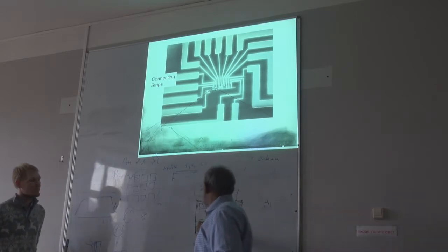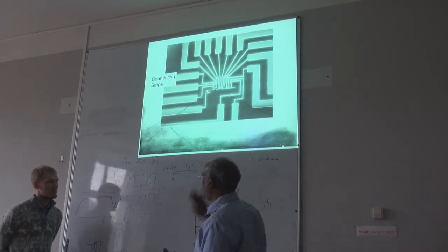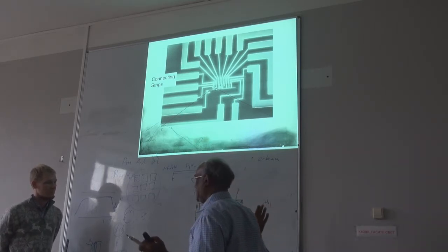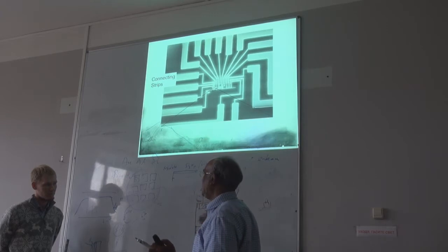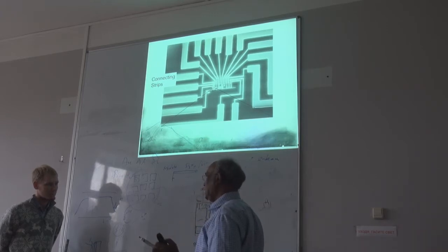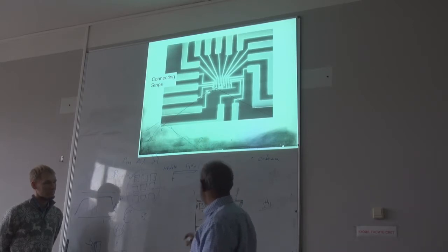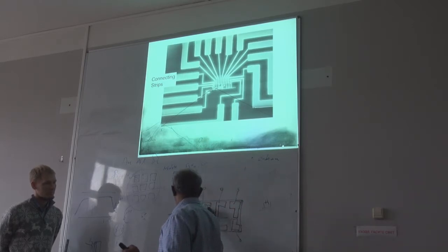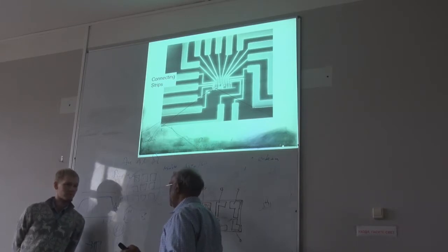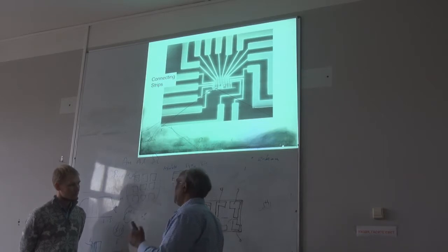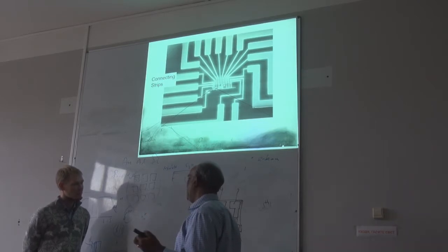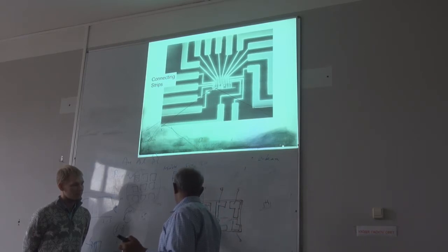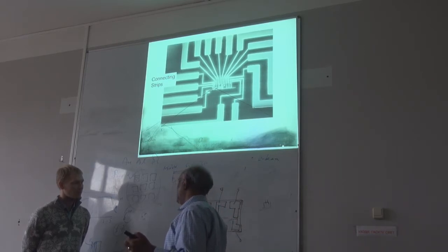Now, on this one I have to put my photoresist. So then, no mask here. So I just write E-beam. When you write E-beam, I can write from here to here. This is the electron beam. Because this one now is a guesswork, but I know where it should be because of this mark. So then I write another one like this.